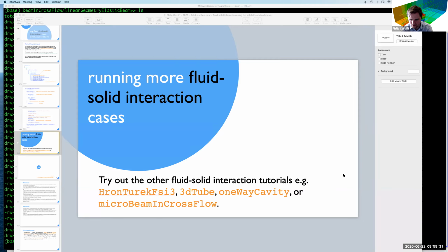Large deformations, and then you see a jump on restarts. So actually, yeah, there's a fix. I don't know if it's in one of the other branches, but when it restarts, some of the fields aren't written out, so the convergence maybe slows down when you restart for the solid. But if you have a case, send me a link on the forum. Maybe you can describe it, and I'm happy to read it and see, when you give specifics, if I can help.